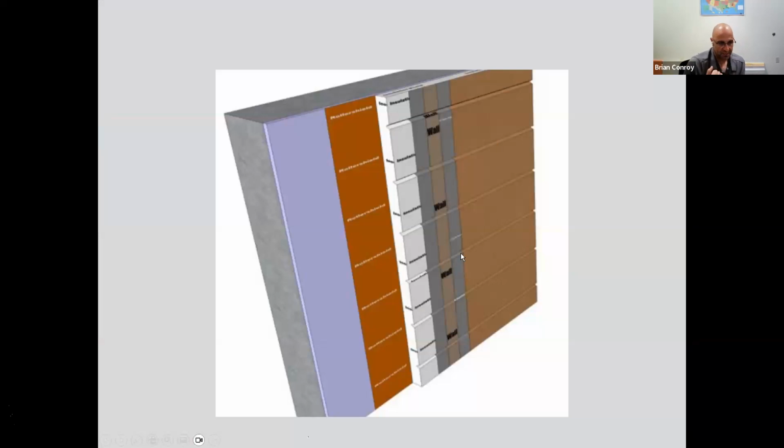Now, I put this one in not too long ago into the presentation, mainly to highlight and show what those V-grooves look like. I've asked many, many times, hey, from an applicator standpoint, how small of a V-groove can you go? Some people will say 1/4 inch. Some people will say they can't go smaller than 3/4 of an inch. Honestly, if you really want tight V-grooves, I would put in your spec extremely tight, 1/4 inch preferred, no more than 1/2 inch, 3/4 of an inch.